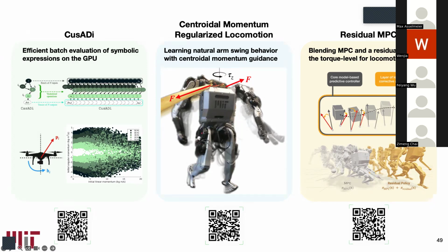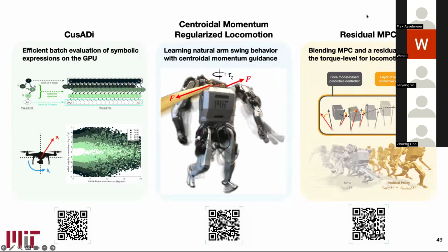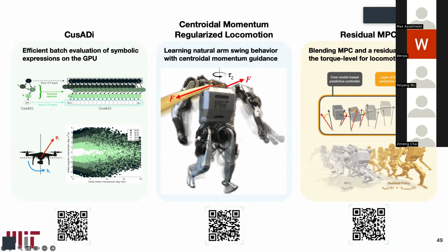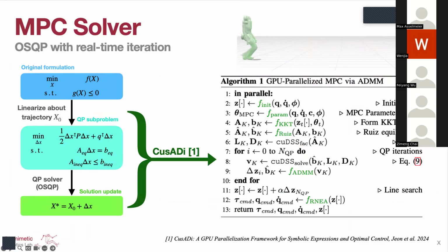With respect to the optimization, I feel like ADMM, so actually, where's my mouse? Let's see here. So we actually use OSQP, which is an ADMM-based QP solver, to get our MPC trajectory. That's how we solve it. I think just empirically, I've found that ADMM is good for fast, inaccurate solutions, but for highly dynamic motions, I think it's much better to use interior point or penalty-based methods.